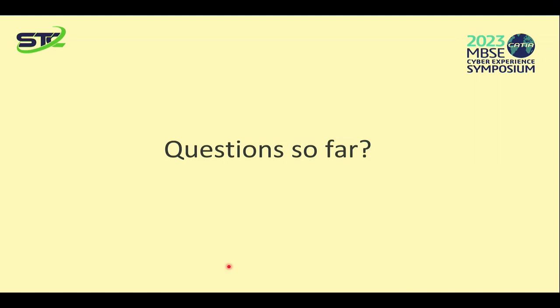Yeah, it's definitely possible to do co-simulations. That is something that is very easy to do, actually. If you wanted to use those constraints and have those modeled as an M file in MATLAB, you could drag that in directly to a parametric, and then MATLAB will execute that for you. So it's easy to do that. There's a native integration from Cameo, and it is very nice to use if you like having MATLAB perform those calculations. But what we found was we didn't need to have MATLAB involved in this case.